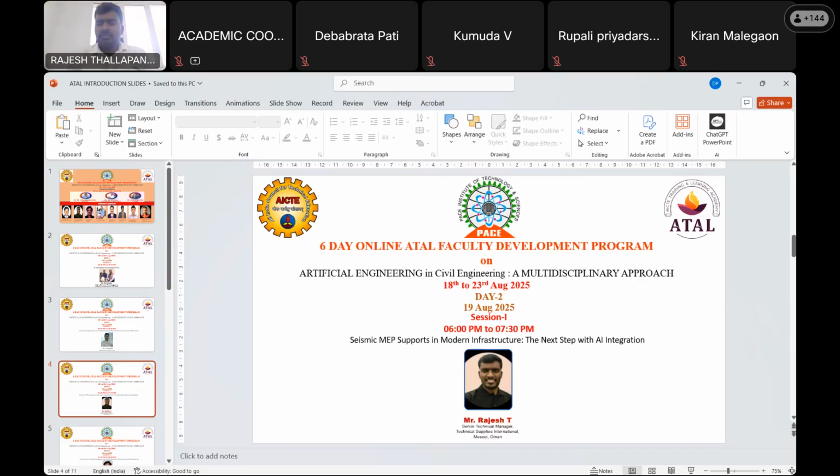There was a question from Sai Kumar Reddy: why are we providing seismic bracing for non-structural elements? This is what I had presented. See, a non-structural element is what actually creates more damage than a structural element. Your structural elements are beams and columns, which we call the skeleton of the structure itself. The non-structural elements are your interior finishes, your equipment, furniture, all these are